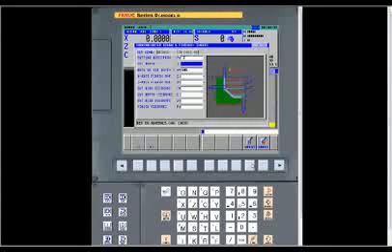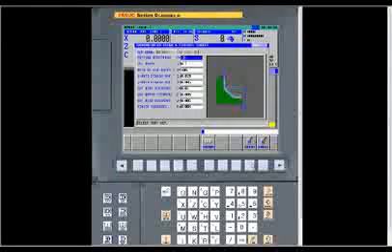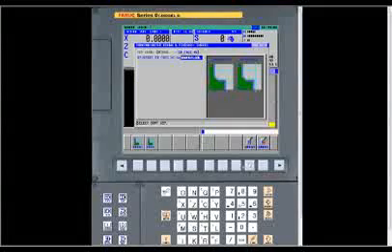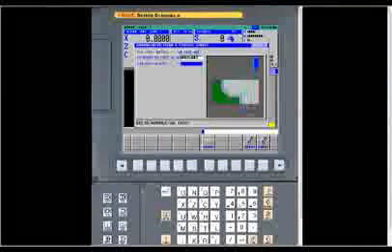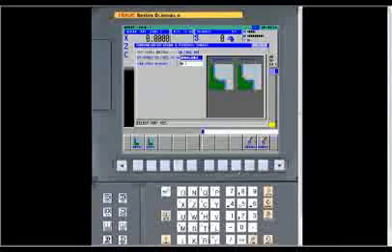So again, Z minus our cut direction. 0.1 is our depth of cut. Finish stock 0.015 on this side. 0.005 on there. Our feed rate is 0.01, 0.005 on our other two. And then now this time that's for a finished feed rate, 0.004. And it defaults, it retains what we had on our detail. Then we always will say available for the face the end, 0.1, enter, and then insert.